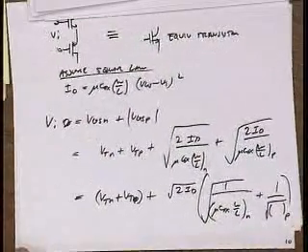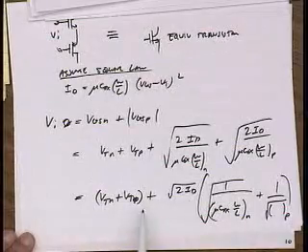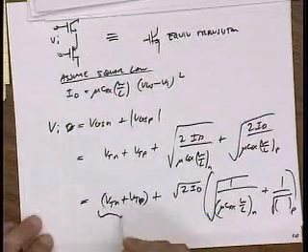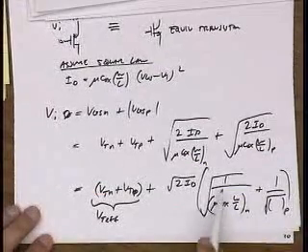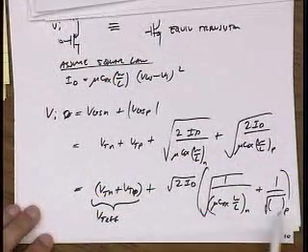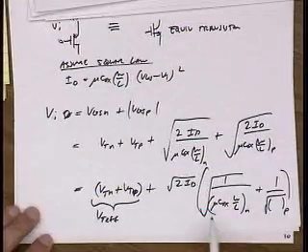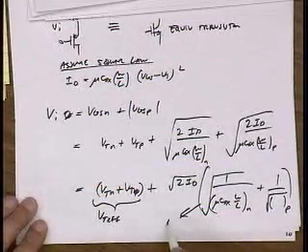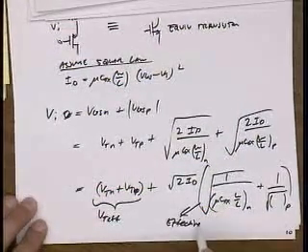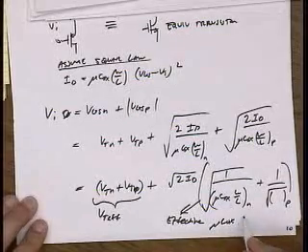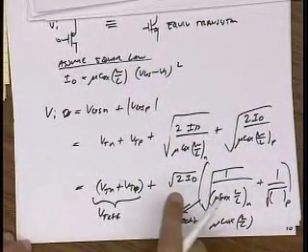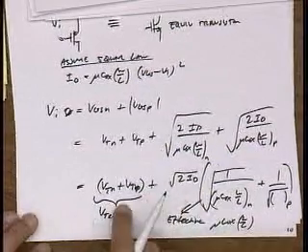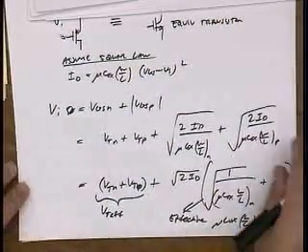you can see that this looks a lot like another square law transistor, where this is VT effective, and I can just lump all this together and say that this is some effective mu Cox W over L. Right, functionally they're identical. I have threshold plus square root of current.